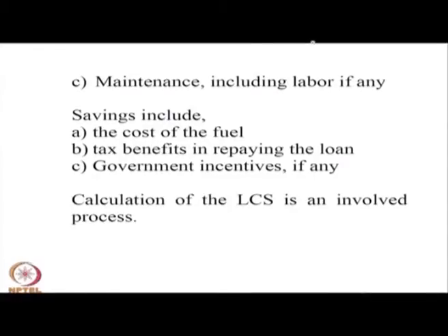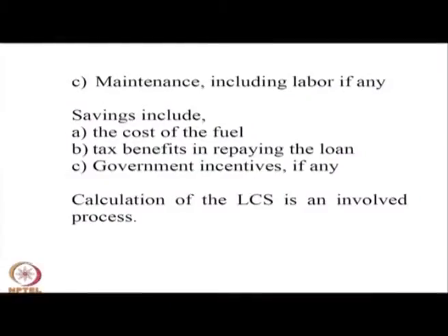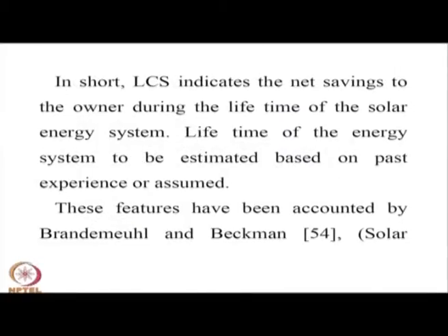So, in general, the life cycle savings, as we have explained, is the amount of money that the system is going to save the earner during the lifetime of the solar energy system. The calculation of this is an involved process, because the fuel prices do not remain constant, the interest rates may not remain constant, the auxiliary power rate may not remain constant. So, all these features have to be taken into account, of course, assuming a certain scenario.